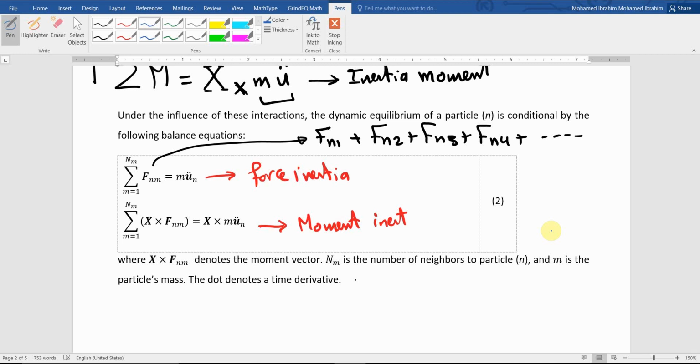The first one is that the material is homogeneous. The second is that the material is a composition of an infinite number of particles. And the third is that each one of these particles is a point. If we change these assumptions, we end up with more advanced mechanics, for example micropolar mechanics, where we consider the particle as a volume element that can rotate. But in classical mechanics, the particle is just a point that can only move. Point means it has only one type of degree of freedom: it can move along x, y, and z. So in total, 3 degrees of freedom for the particle.